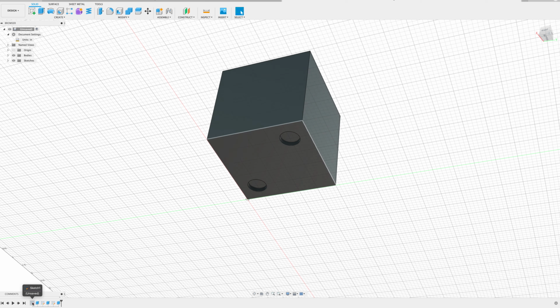If you remember, I started by drawing a square, we extruded it into a cube. Then I created a new sketch, which was the number 1, and then I extruded it. And then I drew the 2 circles, the 2 side, and then I extruded it. Okay, and so now I would do that 4 more times. So that just shows you the order that I'm doing things.